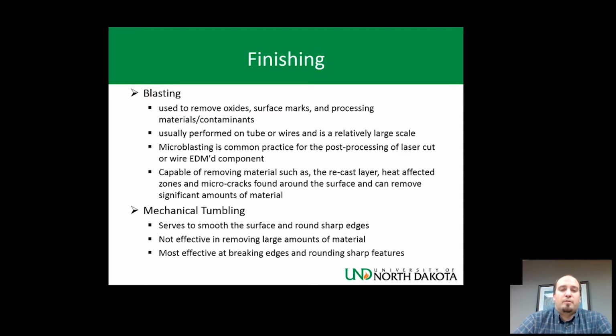SMAs can also undergo blasting. Grit blasting and microblasting are methods used to remove oxides, surface marks, and processing material contaminants from upstream processes such as drilling, heat treatment, laser cutting, EDM, or localized heat processes.